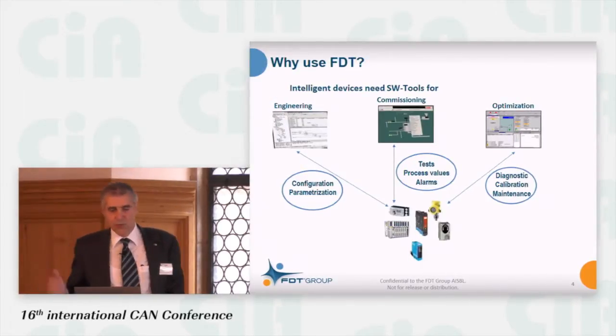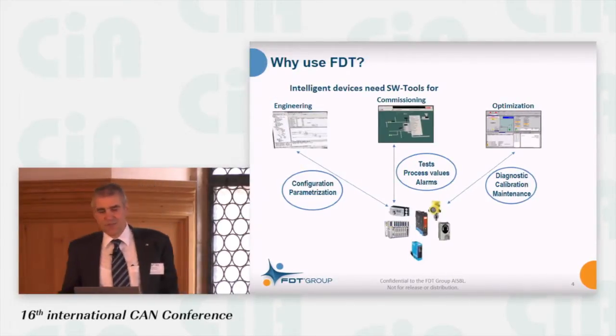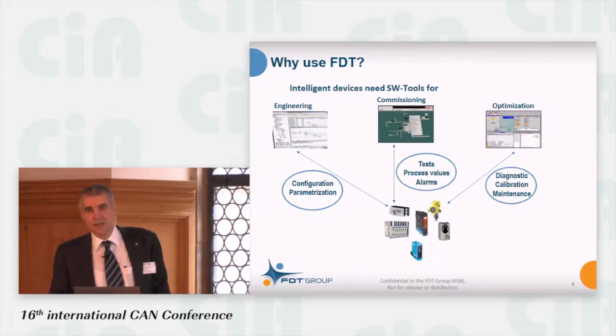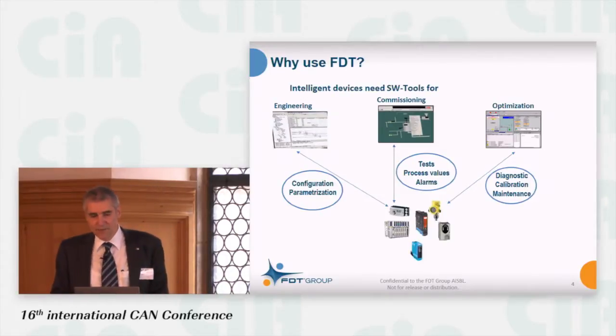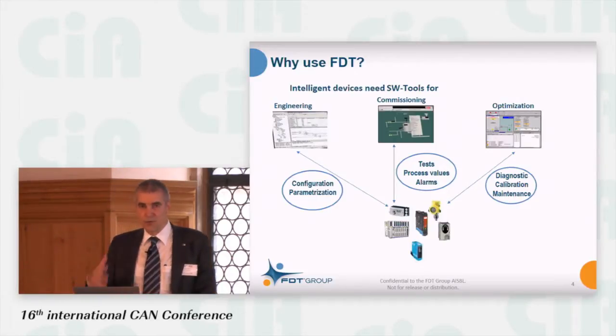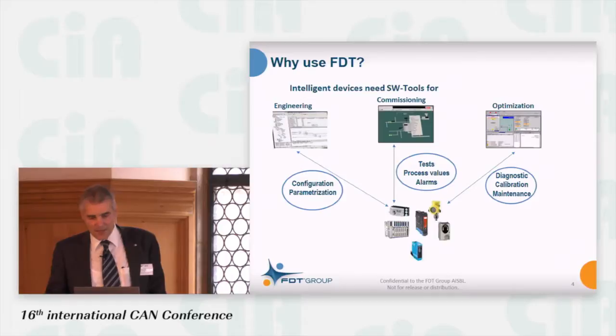So why do we want to use FDT? You know today the devices are more and more intelligent, have more and more parameters, so they need to handle it with tools. They cannot use anymore a screwdriver as in the past. So therefore you need tools for the engineering of these devices, for commissioning, also for optimization, maintenance, diagnostic.